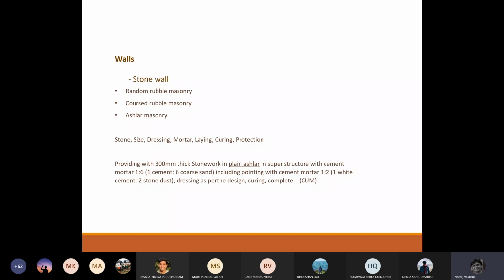But when we are constructing, for example, stone masonry, we generally keep it exposed. In brick also, when we keep exposed brick walls, then we have to mention pointing with cement mortar or whatever it is. Basically, we are securing the joints, because joints are the most prone to water leakages and everything. So instead of keeping them exposed, we generally use cement mortar again to cover it up.